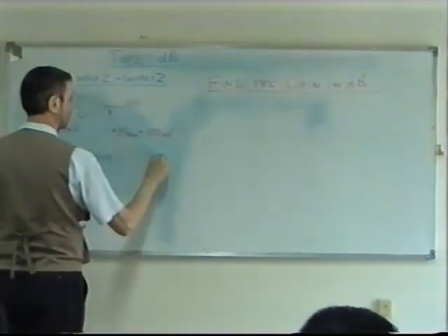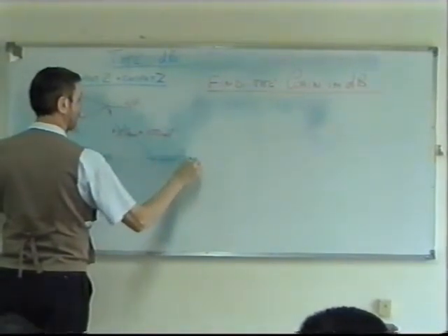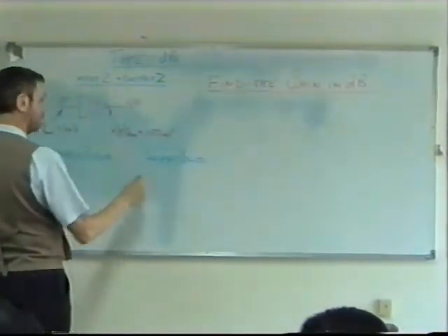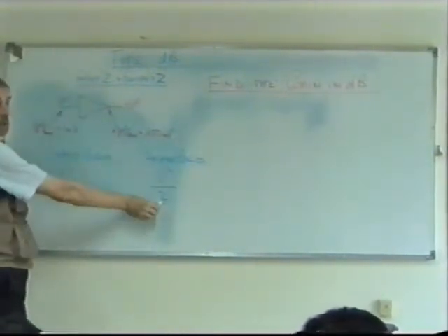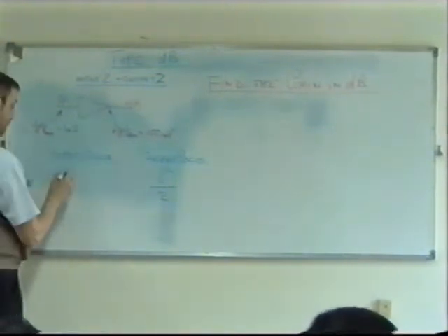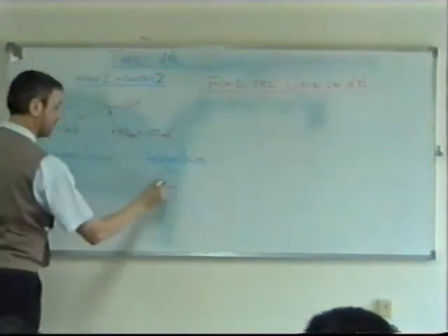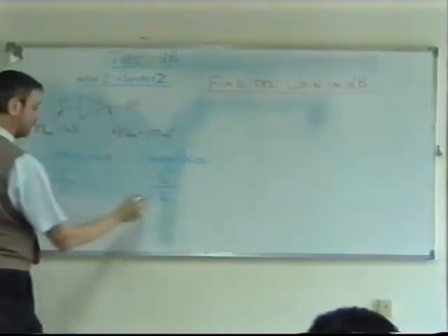And the output power is also equal to V squared over the impedance, but in this case it's the output impedance and output voltage, versus the input impedance and input voltage. So it's V out squared divided by V input squared, because the impedances cancel, don't they? That's why you didn't really need to know the impedance to answer the question.